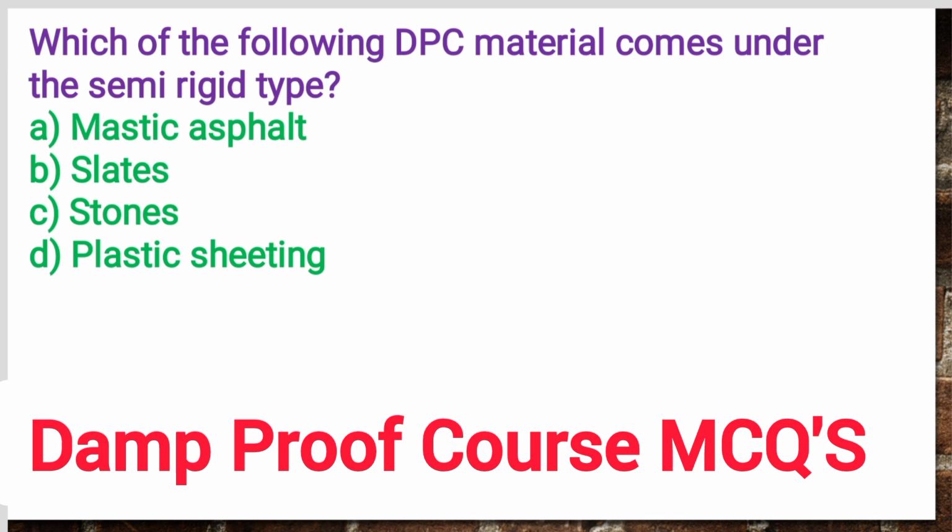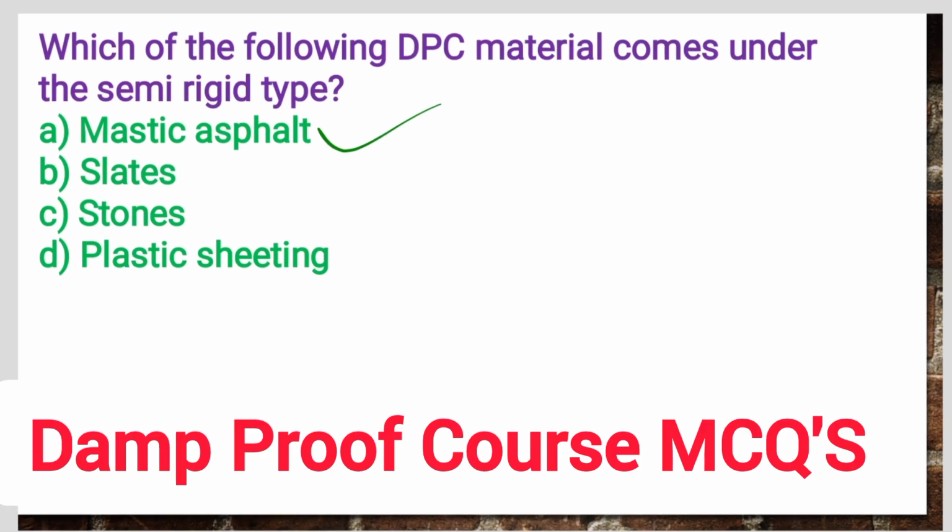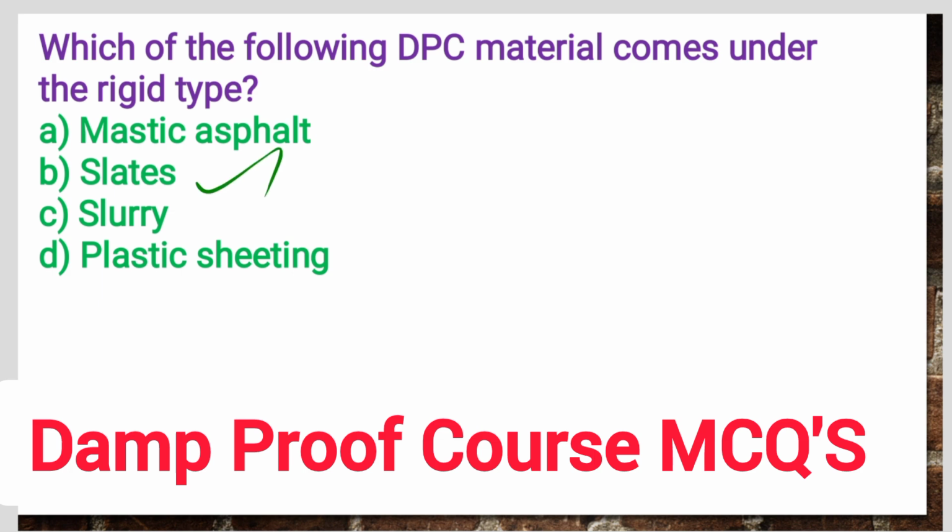Next question, which of the following DPC material comes under the semi-rigid type? Option A, mastic asphalt, option B, slates, option C, stones, option D, plastic sheeting. So the correct answer is option A, mastic asphalt. Next question, which of the following DPC material comes under the rigid type? Option A, mastic asphalt, option B, slates, option C, slurry, option D, plastic sheet. So the correct answer is option B, slates. In case they are asking semi-rigid type, that is mastic asphalt; if the rigid type, it is called slates.